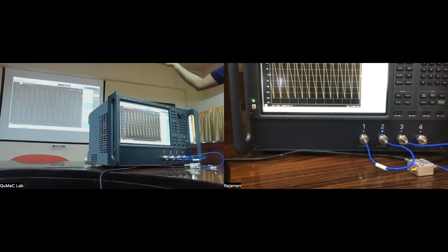If I put a resonator at the end of a cable and do a measurement like this, I'm going to be completely obscured by this trivial phase shift. So by entering this number here, I'm just telling the instrument to basically subtract out the effect of this length of coaxial cable. Ideal coaxial cable. It cannot do anything. This will not affect the losses or anything in the cable. So that it can do this because the velocity is constant.